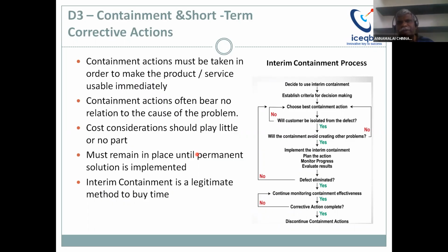So for example, you have delivered some defective parts, the customer is complaining that defective parts have been sent, and already 5 lots have been sent to the customer. Then you immediately send enough people to the customer's place so that they do the sorting there. And then you make an analysis of the extent of damage in the company. Maybe already 2 batches are there in finished goods. So again, you put some persons on sorting in the finished goods, and whatever is in process, again you have to check.